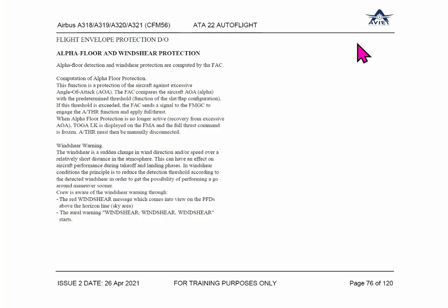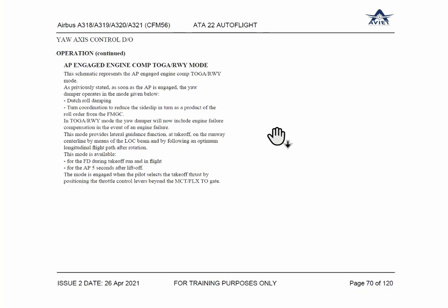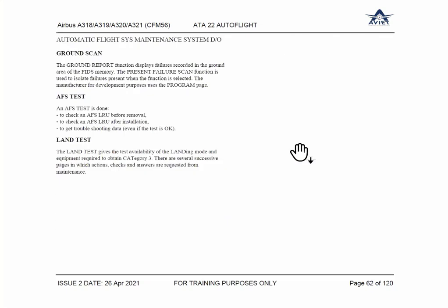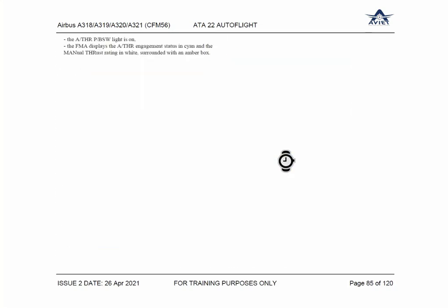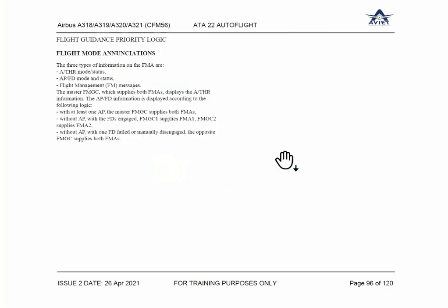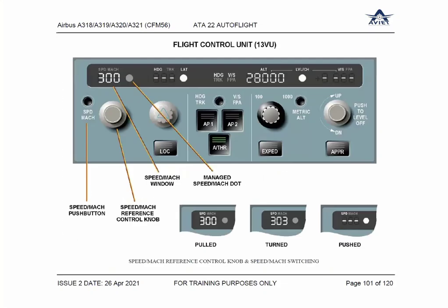You remember the lever position and the auto thrust, what is the difference? What is the role of the lever in auto thrust condition? The lever will remain; the position won't change. That is one thing. What else? It should be on the climb position, between climb and MCT.